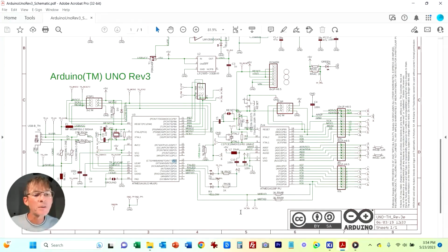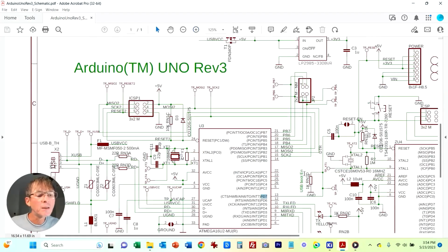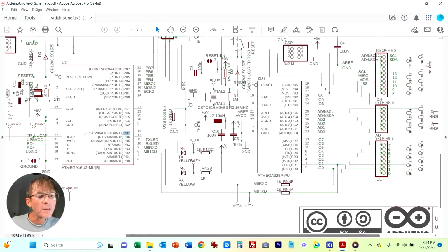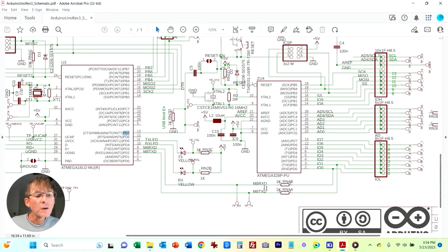So let's pull up this schematic here. Let me zoom in down here on our lines. It's these two lines here. This first one here they're calling M8. I'm not sure what the M8 is, but they're calling this the RXD line, and you can see it goes to an RXD on our primary microcontroller. Generally you want to name everything in terms of the primary, the master microcontroller.